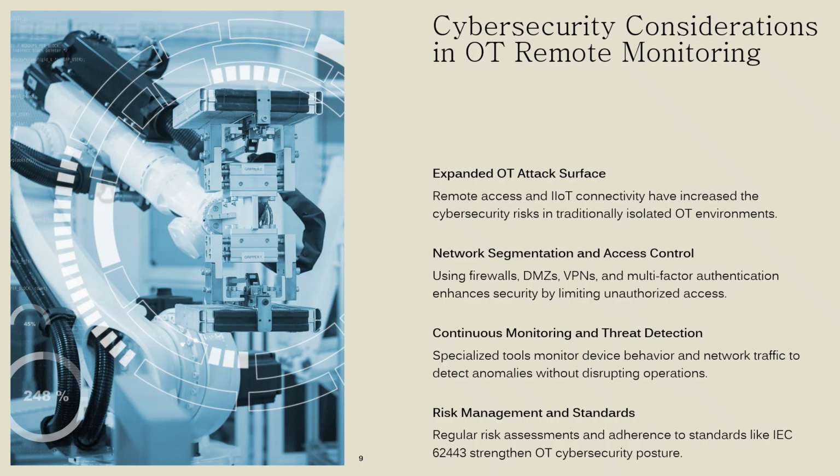OT networks should be segmented from IT and external networks using firewalls, demilitarized zones (DMZ), and secure gateways. Remote access should be tightly controlled through VPN, multi-factor authentication, and role-based access control.